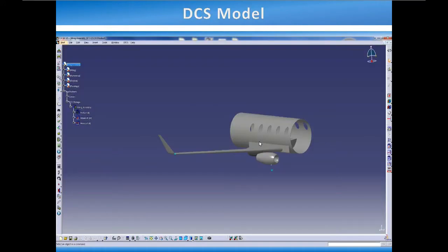You can see this model was not built with actual data, and a few realistic assumptions were made, like material properties of the wing, assembly sequence, all the tolerances used, weight of the engine, and a few others. If you see 2 points here, these are the measurement points. These represent the ground clearance measurement, and this point at the end of the tip represents the wingtip displacement.